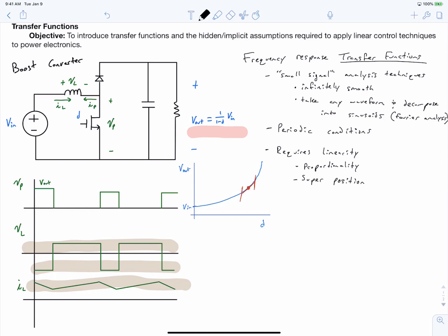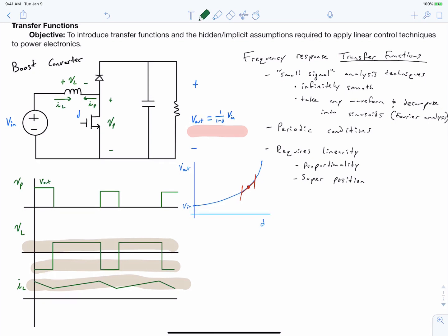It means that we can look at a system that is operating at nominal conditions, and we can add to its input some delta D amount, and we can study that by considering two separate systems. We could study one system that just has an input varying by delta D, and another system that is at its nominal condition, and sum the response of the two.